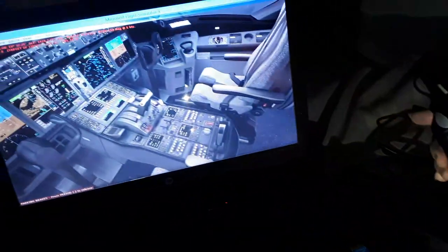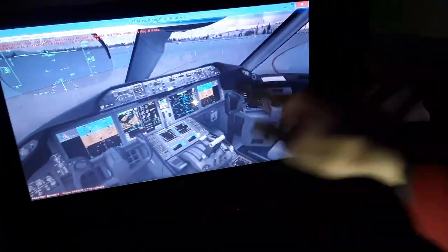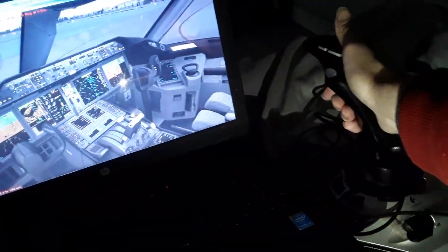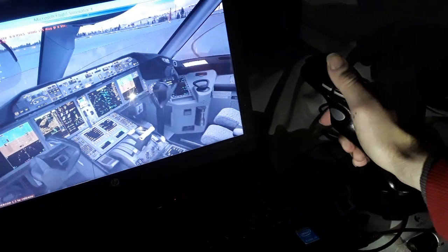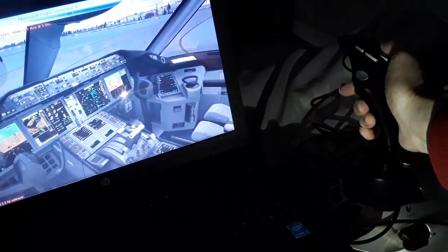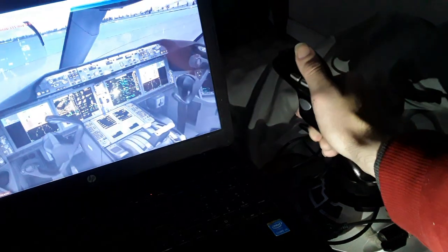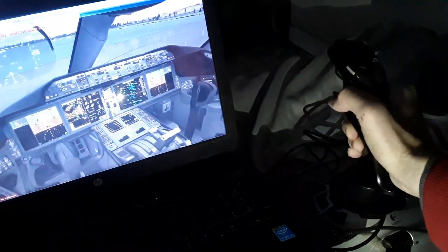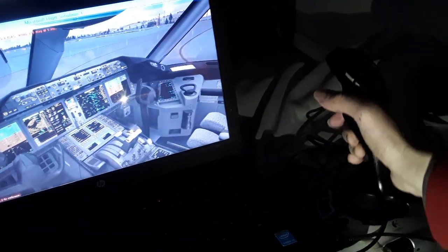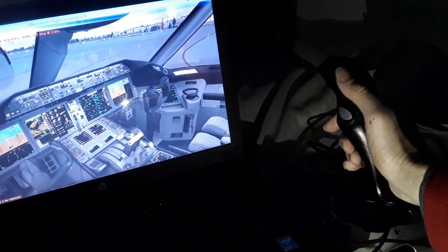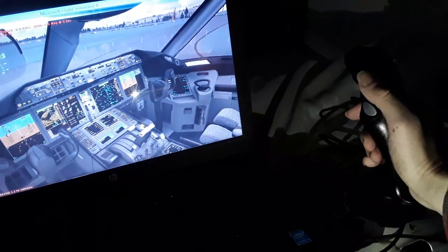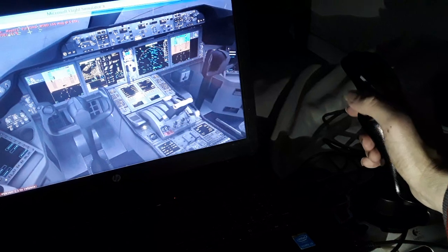You can see left and right, captain and first officer move together. They're interconnected in flight. All flight controls move together in the Boeing aircraft, or Boeing 787 in this case. They don't move independently like in the Airbus, where you have the side stick priority for using either the left or right side.